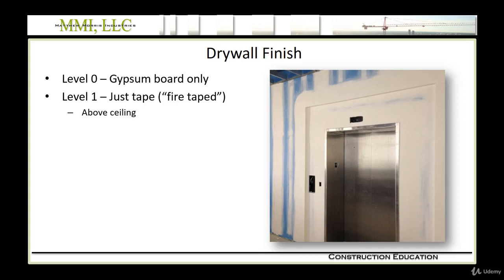So for small quantities, joint compound is applied by hand with a drywall knife in the joint. Then tape is placed by hand in the mud. And tape is often a paper tape or a mesh type tape. So that process is rather slow. That's how I do it in my basement when I'm refinishing my basement.